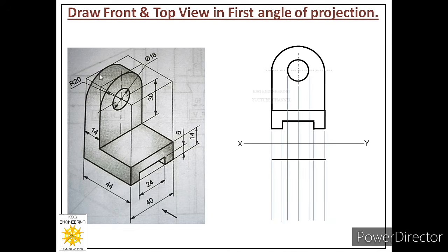After that, we will complete its projection. That will be a rectangle only. So from here, we will draw a width of 14 millimeters. Then again, we will draw this edge, though it is curved edge, but from top it will look like a line. And that line will have a length of 40 millimeters. So from here again, sketch a continuous thick line of 40 millimeters and complete its view. So you can see when we look at this curved surface from top, its projection will be a rectangle only.